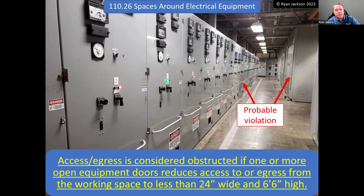Open equipment doors must not obstruct the means of egress. Now, when I say means of egress, I don't mean Chapter 10 IBC exit discharge. I'm not talking about that. I'm saying your ability to leave the working space in front of the equipment, okay? It's not obstructing, you know, the exit access corridor and all of that jazz.